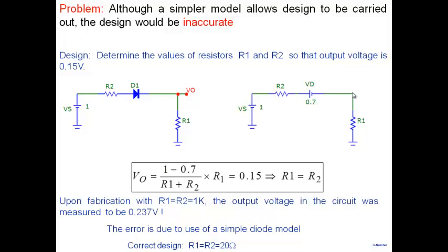It's very time consuming. And a greater problem with this is, suppose I had 4 diodes. Now, simply changing one element is not going to do your job. You have 4 or 5 elements that you may have to simultaneously work with. And remember, each time you change a component, R1, R2, R3, you have to go to the lab, pick out those resistors, read the color code, red, green, blue, or whatever, read the value of the resistor, put it there, measure again. Imagine the kind of time. The whole exercise is very time consuming. Not only that, things get a lot worse.